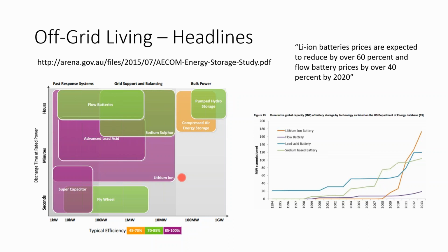If I can buy a 50 kilowatt hour flooded lead acid battery bank, it may just be a matter of controlling my facility energy so that instead of having an air conditioner that clicks on and clicks off, I get a variable frequency air conditioner that costs more money up front, but it's able to run at a constant power level throughout the entire day.